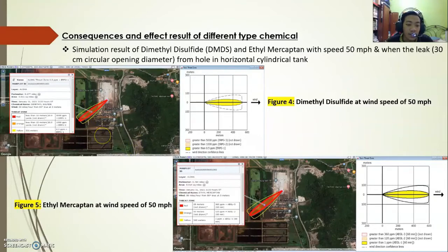However, the events modeled by ALOHA are the flammable area of vapor cloud and the blast area of vapor cloud. There is no potential blasting resulting from explosion in this scenario, as the LOC was never exceeded, since no part of the cloud is above the LEL. It was less than 10 meters of dispersion.